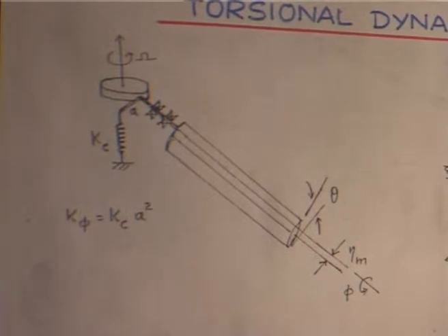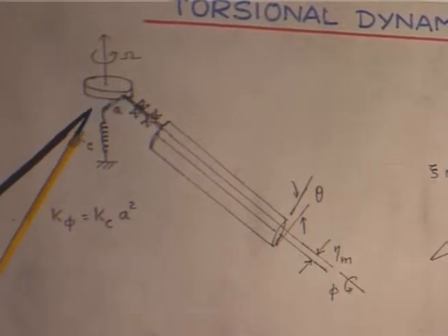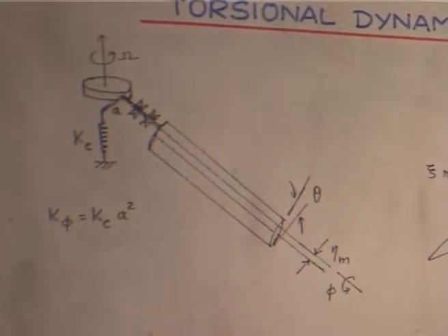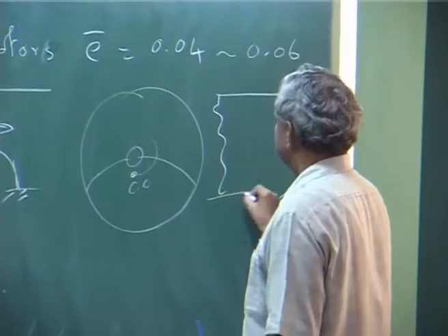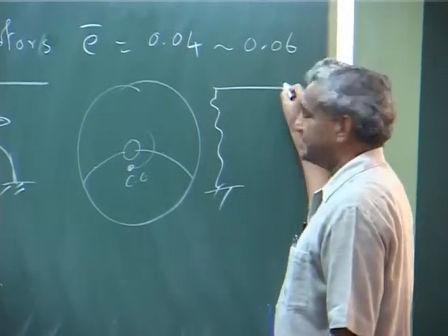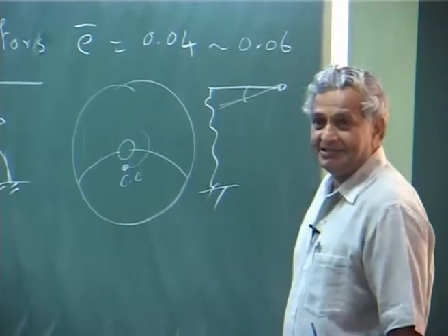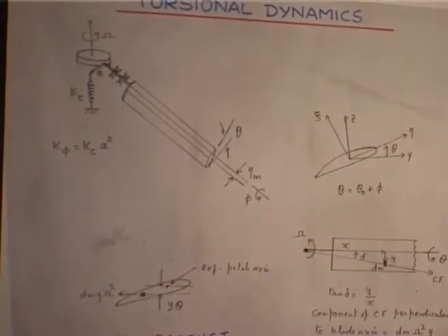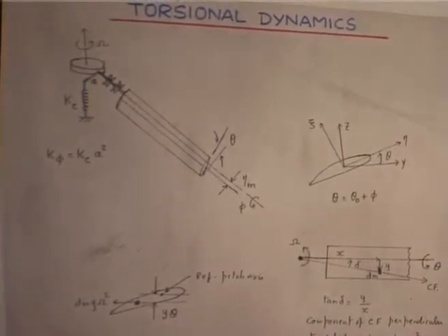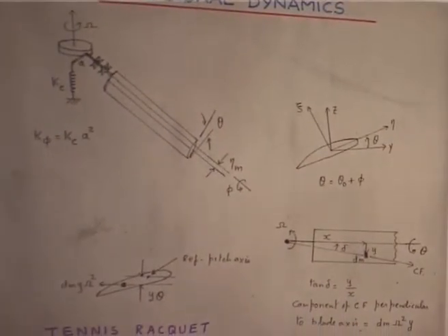And this control system stiffness Kc with the offset A, because there is a linear spring here. If you have a hinge, then you know that this into this distance is the angle. If you take it in terms of angle, that will be control stiffness into A square, that offset. Then you can add the bearing torsional stiffness. I have put everything into equivalent control stiffness.